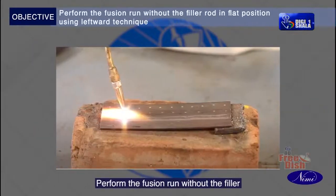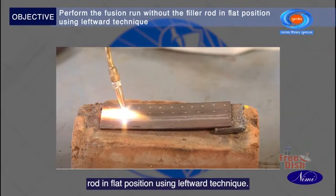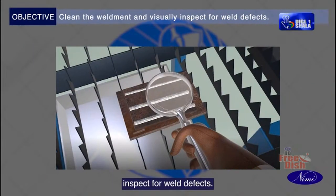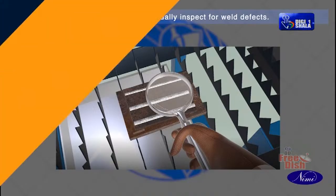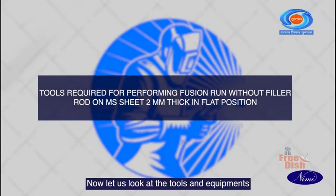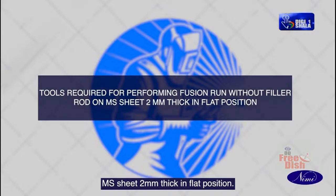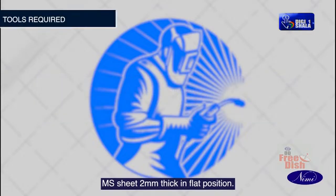Perform the fusion run without the filler rod in flat position using leftward technique. Clean the weldment and visually inspect for weld defects. Now let us look at the tools and equipments required for performing fusion run without filler rod on MS sheet 2 mm thick in flat position.